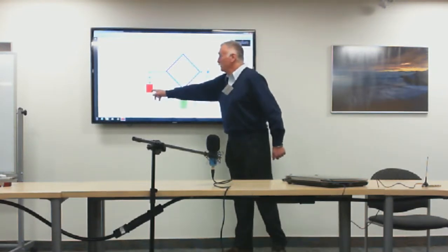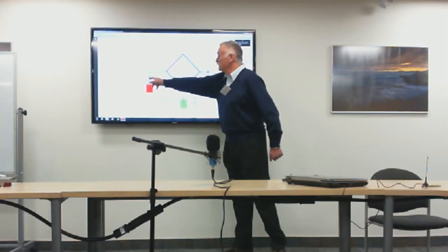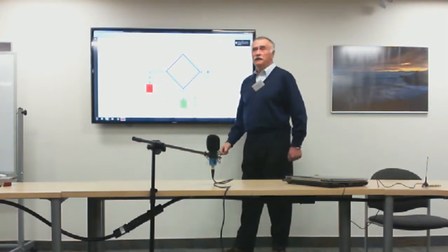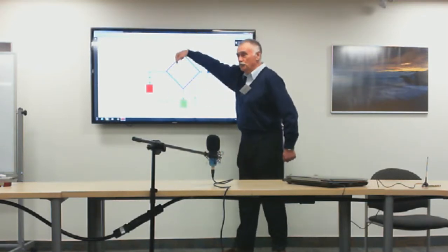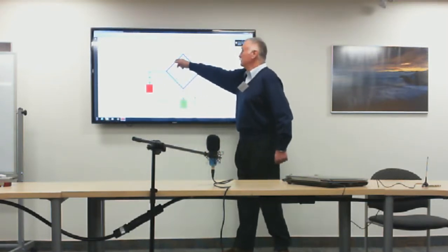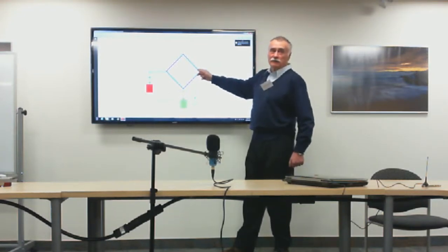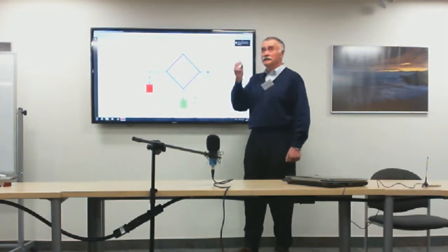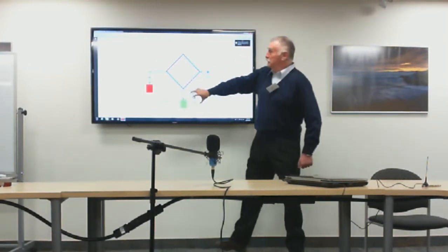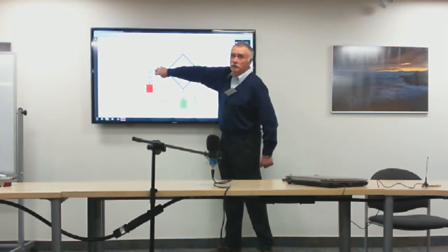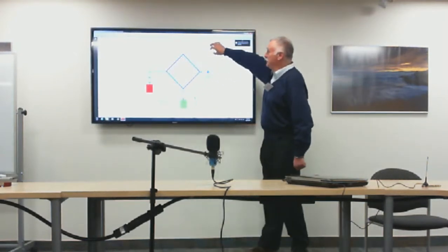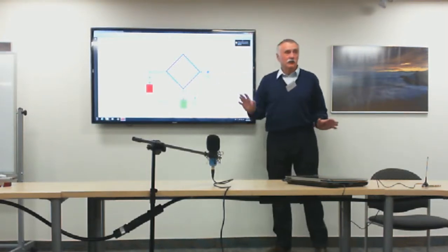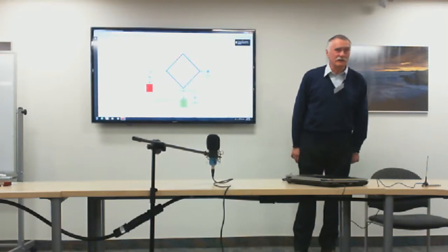So then power from the transmitter goes through this reverse connected diode, which does not matter for AC. The radio frequency would go through it both ways, would travel through a half wavelength section, 1/4 and 1/4. And now a half wavelength section of coaxial cable, whatever impedance you have at one end, like 50 ohms, that impedance is repeated at the other end, like 50 ohms, to be a match to the antenna. So that was transmit. Now we want to receive.